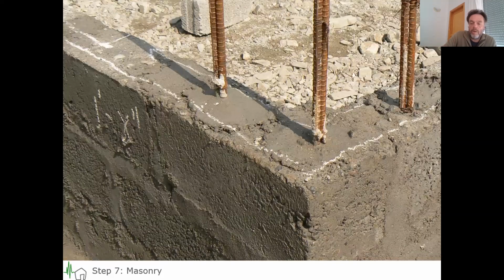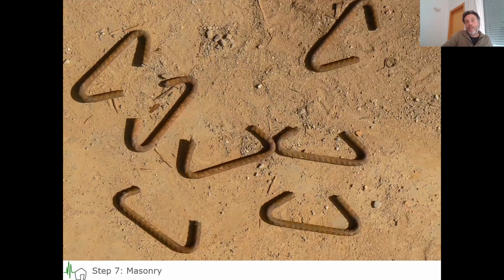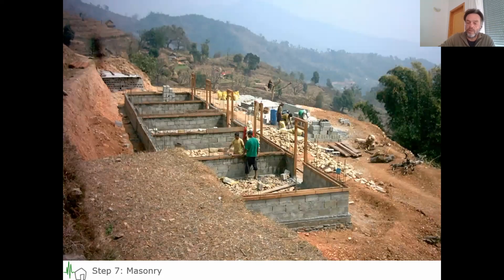And also this is being marked and this is being bent. So this is rejected. This is not correct. So these little stirrups are already bent outwards. And during a seismic event, they will very easily open and crack your beam. So they really have to be bent up to 180 degrees inwards. Like I said, it is constant supervision and repeat to get the quality that we really wanted.